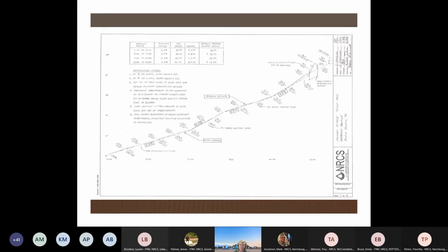So here's an old example back when we did it on paper, but this is just a waterway. The outlet is always station 0. I think there's maybe a culvert or something that is collected and conveyed through this waterway would be the station at the furthest most point, like station 15 plus 50. So they've got really good information with each reach. A reach is a section of the waterway that has the same slope. So each reach is going to have a different depth and width and maybe a different lining.